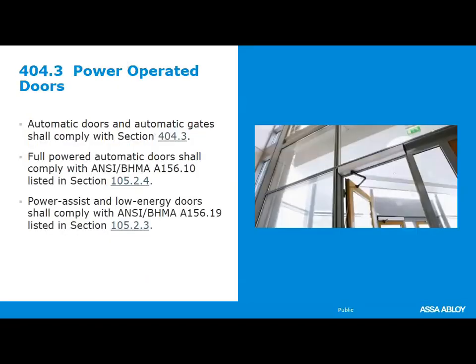Power operated doors are not required yet by this standard. However, if you use them, they must meet the requirements of the standards for either high energy or low energy operators. So full power operators would meet the requirements of ANSI BHMA A156.10 and power assist and low energy operators complying with ANSI BHMA A156.19.